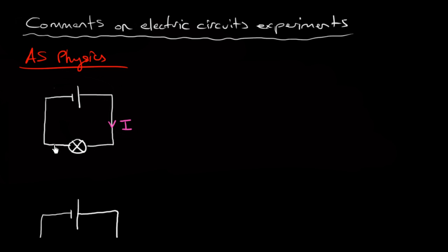Similarly, if you take the potential difference across this light bulb, you'd have to connect your voltmeter across it, and then you would register the potential difference through the light bulb, which should be the same as the EMF of the DC power supply. Okay? So the EMF of that supply, or in this diagram it appears as a battery, would be the same as the potential drop through that light bulb.